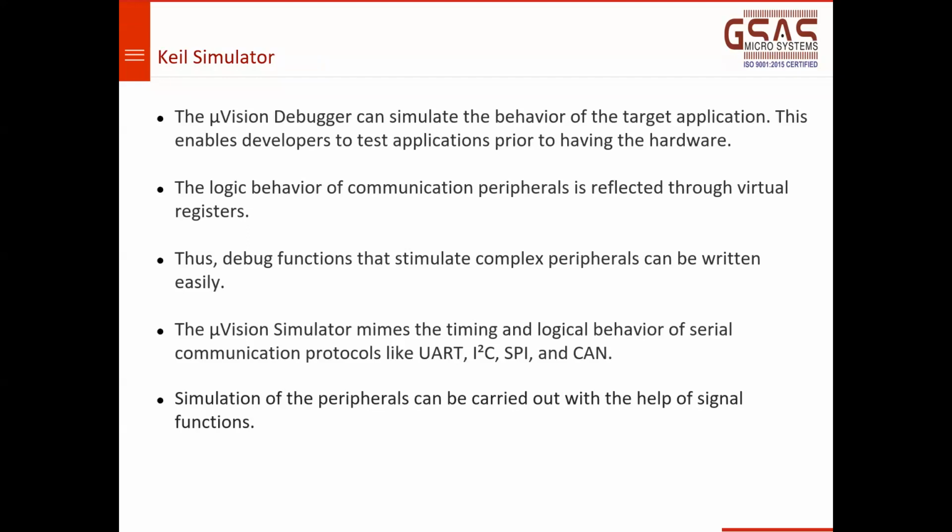Suppose I'm writing a program for I2C. I know theoretically how the peripheral works, but how do you program it in an embedded processor? It is through registers, that is, peripheral-specific registers. For I2C, whatever registers we have for that particular MCU, we use those registers and configure that peripheral. But there is no way you can access the microcontroller pins.